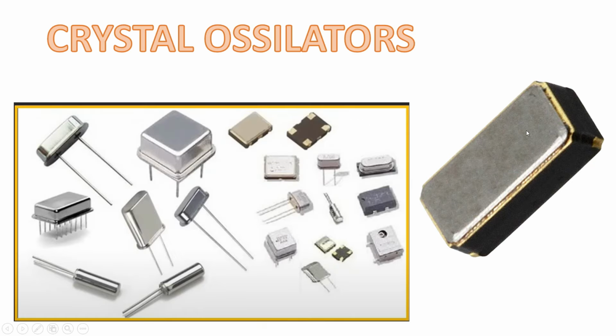Okay, next it's a crystal. Once the V in section becomes active, then the first PCH part, the RTC section, will get enabled because of this crystal. The crystal also gets enabled because of that RTC VCC voltage. Nowadays that comes through the battery. The battery has 3 volts.